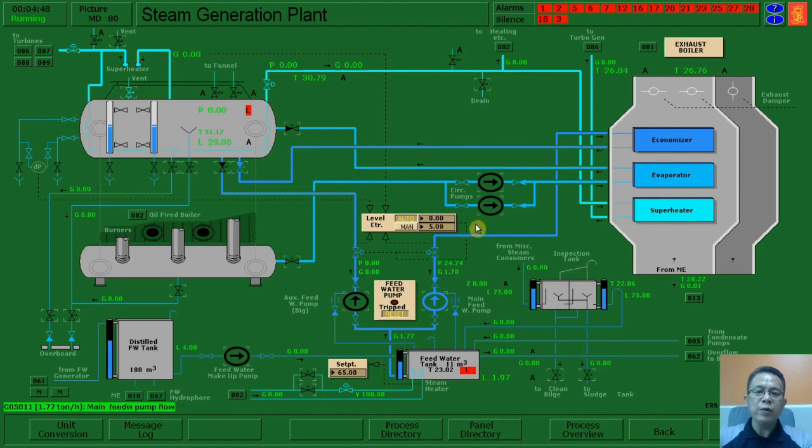And since we have here the circulating pump, we are going to start up the circulating pumps. So, what does it mean by circulation of the feed water? In the boiler system, circulation of the feed water ensures that full circulation of the water is established before the gas or exhaust from the main engine is allowed through the boiler economizer. Meaning to say, we will not let the pipe run dry before the exhaust of the main engine passes through, because it may endanger our pipes.